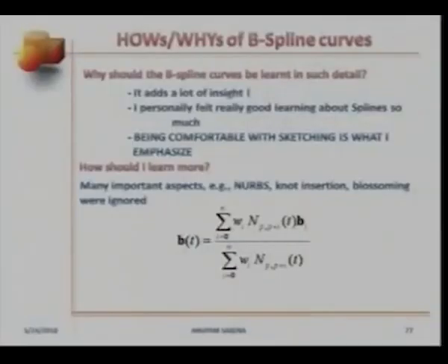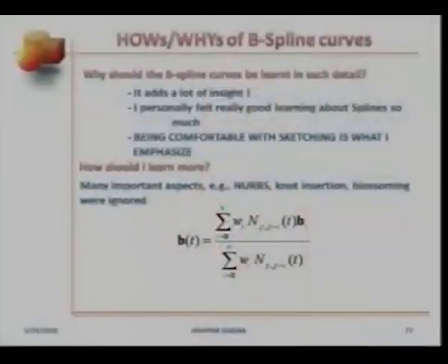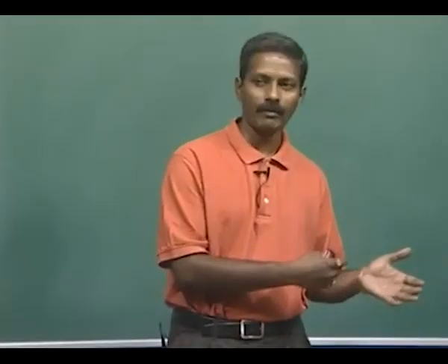For example, we can simply extend the rational Bezier curve model and apply that to define mathematically NURBS, or non-uniform rational B-splines. Now, if you try to relate those two expressions, the expressions are almost identical with a slight difference. There, you are using Bernstein polynomials.